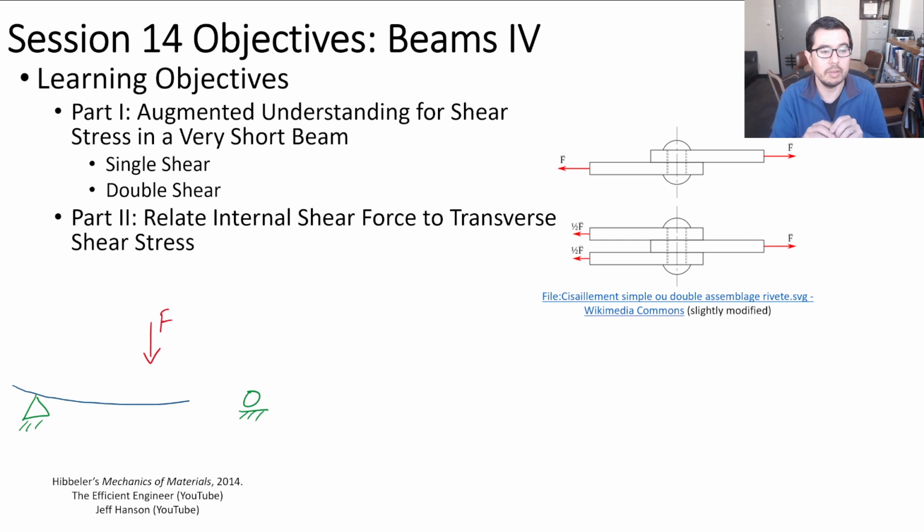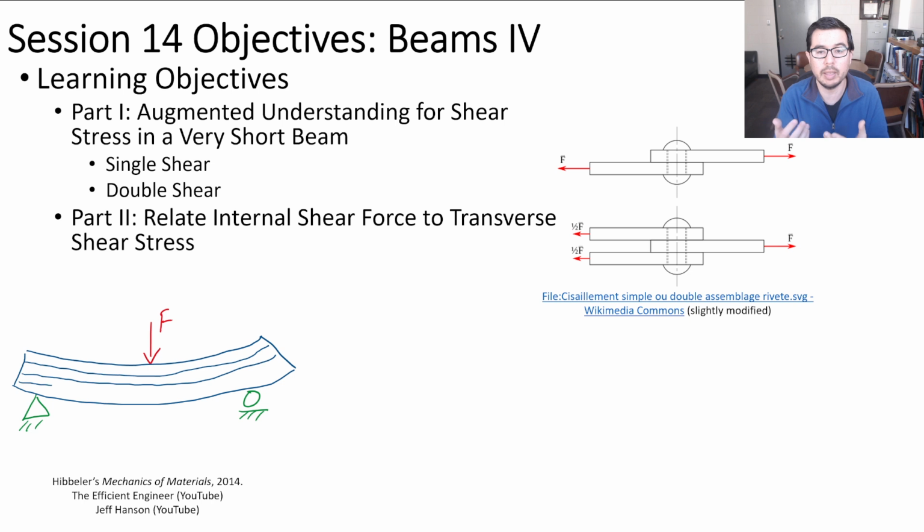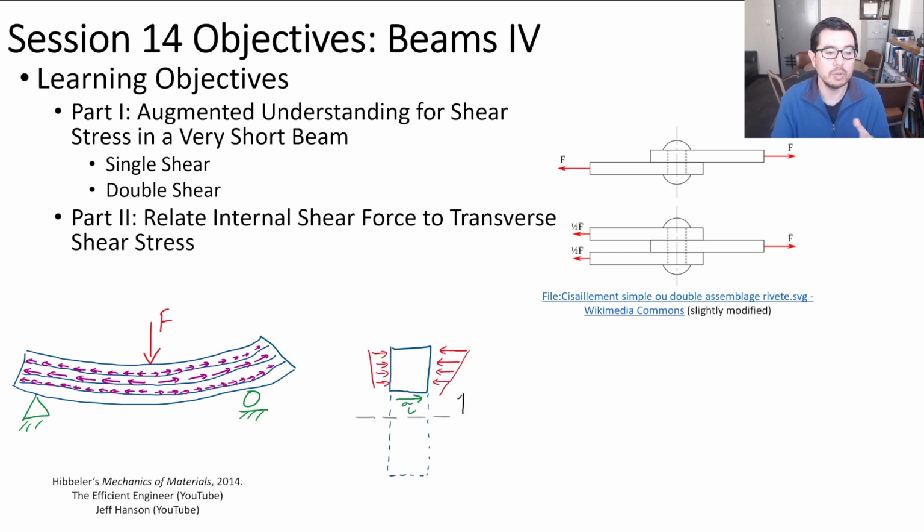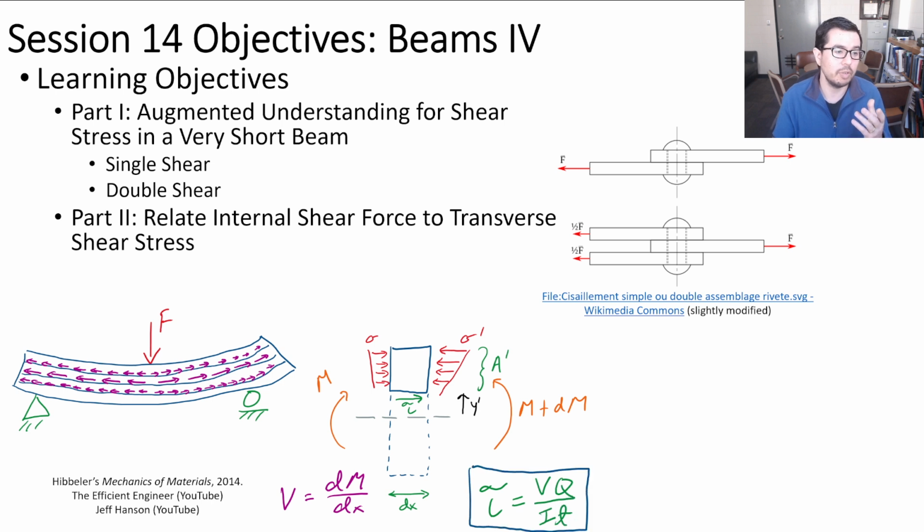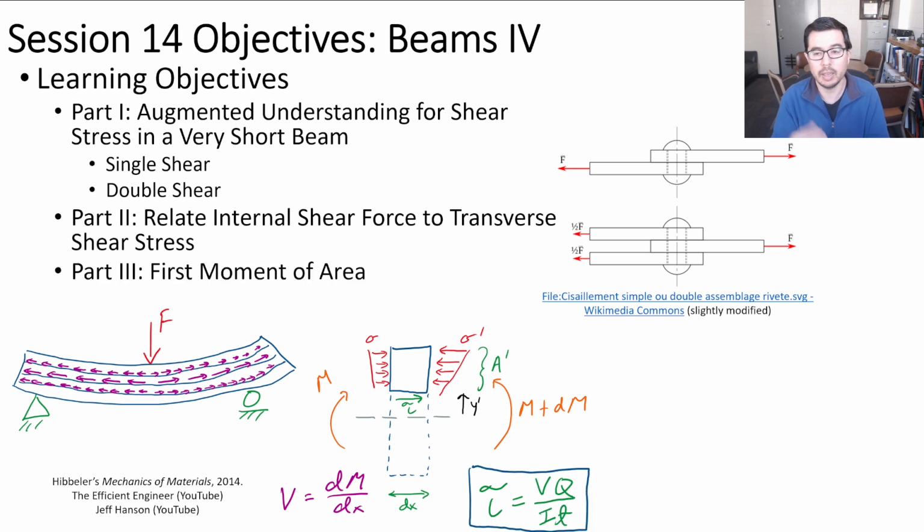Hopefully we also have some intuition and tools for calculating what the transverse shear stress would be as a function of the internal shear force. We've also spent quite a bit of effort describing how the first moment of area is calculated and how that first moment of area affects the transverse shear stress for systems.